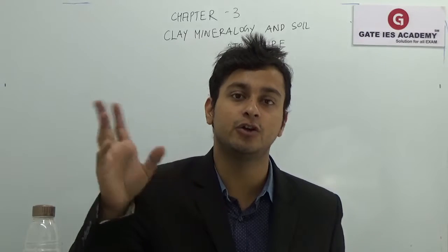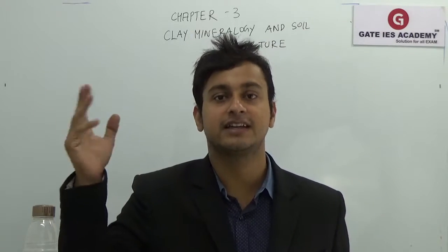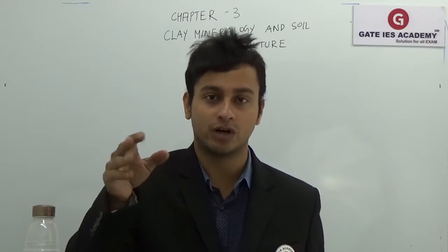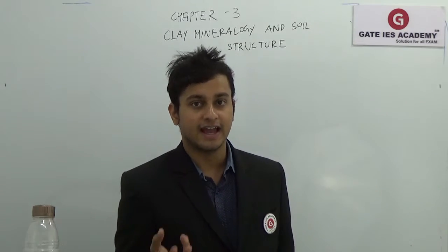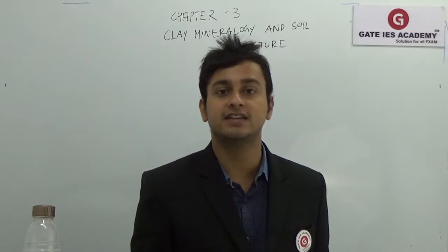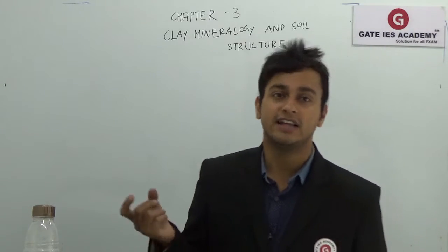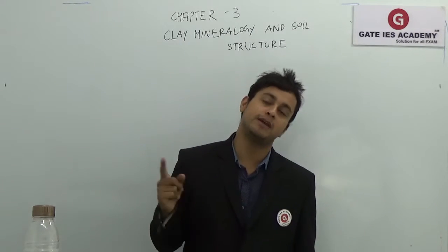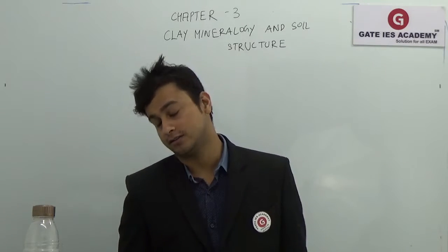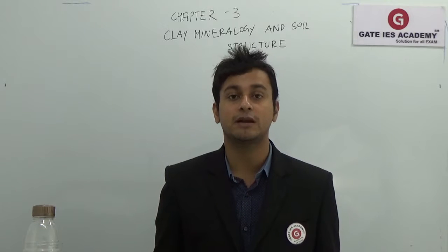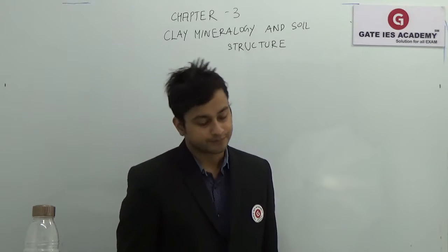There are chemicals which are provided in the rocks, which are coming due to the seas, glaciers, acid rain, whatever it be. So the chemicals come into the rock and therefore the weathering happens, and therefore soils which are formed are called fine grained soils, and therefore their mineralogical composition becomes very important in actually studying the properties of that particular soil.